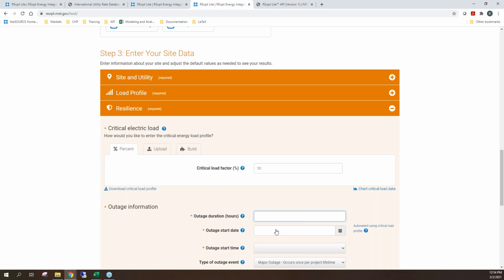And then, on top of that, it says you have to meet this outage with our on-site generation, and then it'll do the economic optimization. So if you're considering CHP in that resilience analysis, it's going to show the value of CHP, versus maybe PV and storage or a backup diesel generator. So it has that baked in. I just wanted to describe the scope of the resilience analysis.